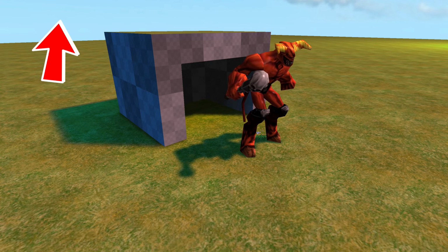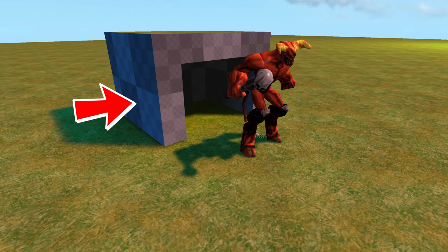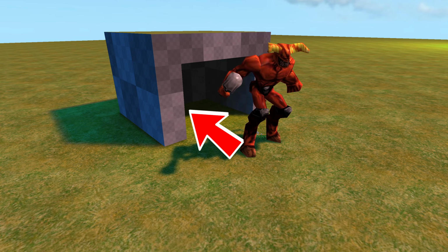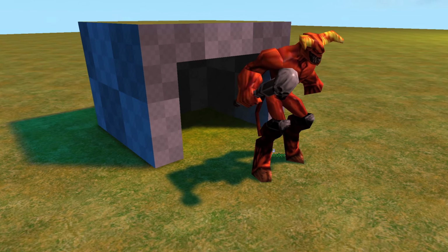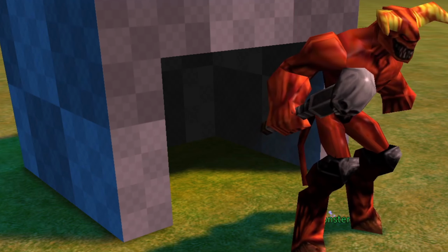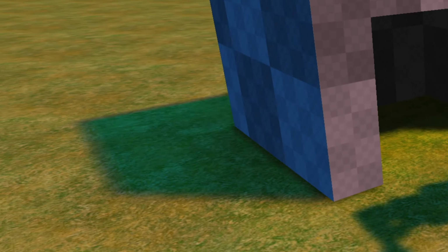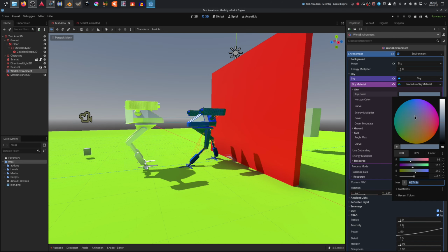You can think of skylight to be the primary color of the sky, which is then multiplied with the ambient color. You can use this to have a more shadow-like ambient light, hence not matching it to the fog or sunlight color, and just keep it dark or grayish, by using the skylight to change the overall tone according to the sky color. In other engines you would probably call this global illumination, while global illumination in other engines also takes the color of surrounding parts of the map into account, which Cube 2 does not.